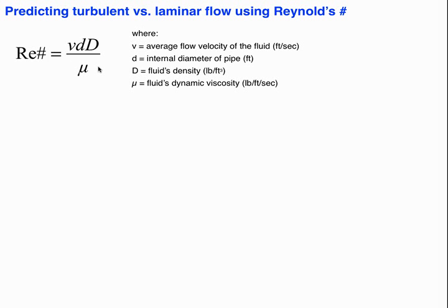High viscosity fluids, like a very cold motor oil, will flow relatively slowly. When we heat a fluid up, we lower its viscosity and it flows faster. Of course, you can see that with something like motor oil. Once you warm it up, it appears, typically the term is thinner, but in fact it just has a lower viscosity. Well, when we heat water, its viscosity changes considerably, and it's easier to move heated water through a piping circuit than it is to move cold water, and the reason is viscosity.